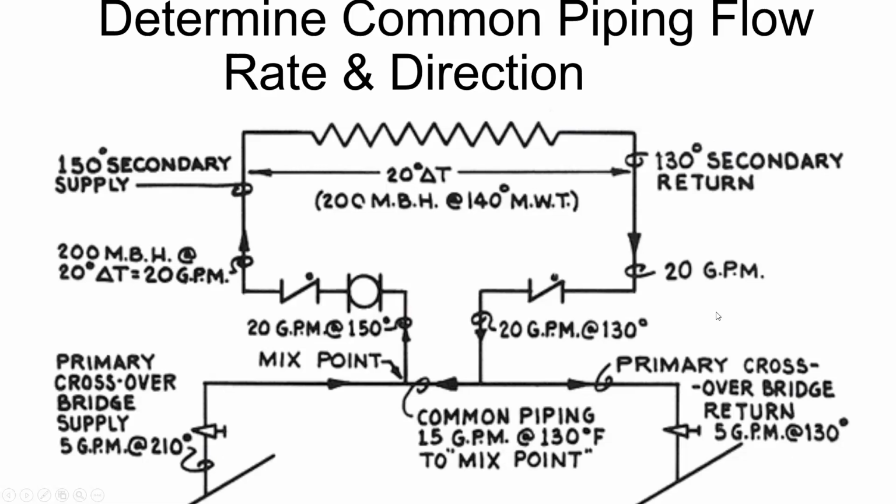Now, as that 200 becomes less and I'm still pumping that same flow, I'm going to overheat, right? So I'm either cycling the pump on and off, very uncomfortable. So then I'm probably going to introduce almost like this crossover. I'm going to probably put that 3-way valve.